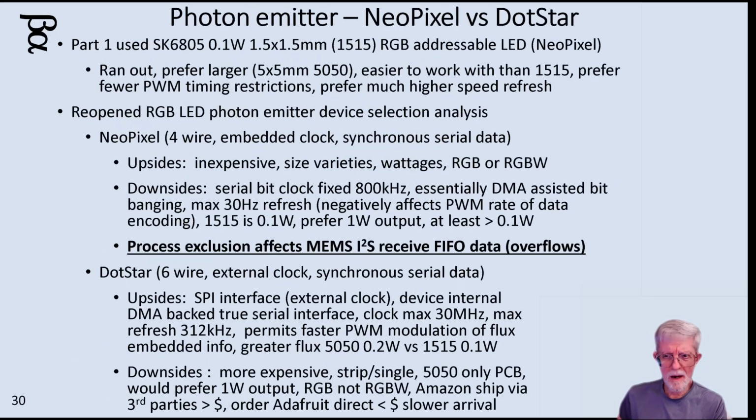Now, you remember me saying I was using NeoPixels and I went with DotStars. This gets into the minutia of it, but basically the driver of the NeoPixel interface made it where I couldn't reliably receive the microphone data. They have different interfaces. They buffer differently, is the best way to describe it.